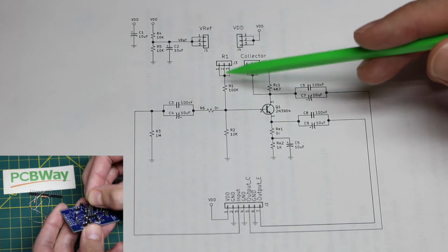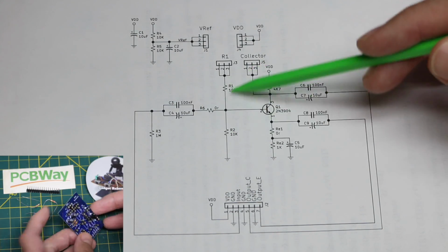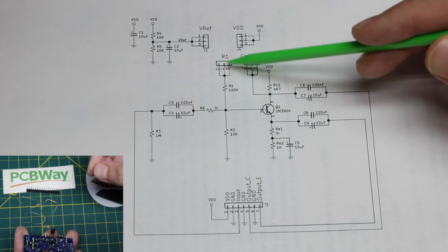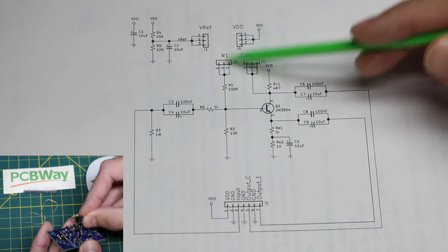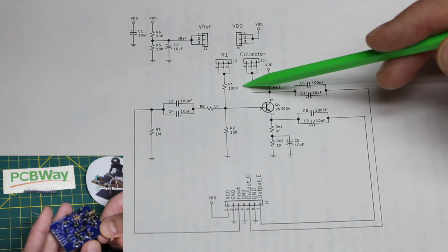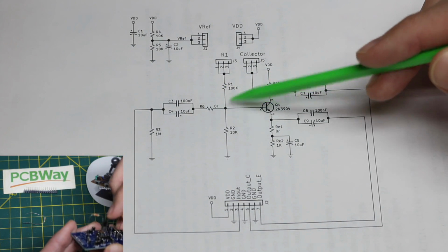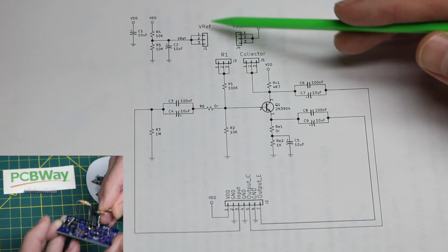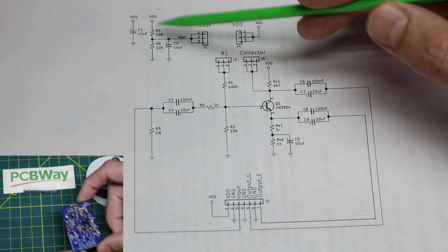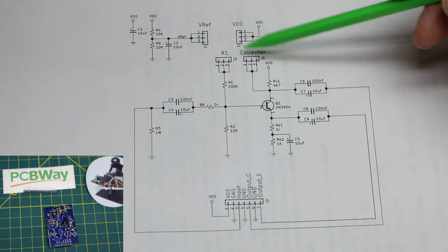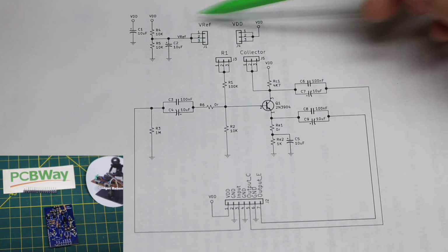And for trying a circuit that doesn't have a voltage divider bias, this top resistor isn't tied to the positive supply, I can put a jumper to positive supply, or I can jumper it so it goes across to the collector for a different feedback structure, or I can tie it to a voltage reference, which I can set up with resistors here. So I just wanted a somewhat universal configurable transistor development board.